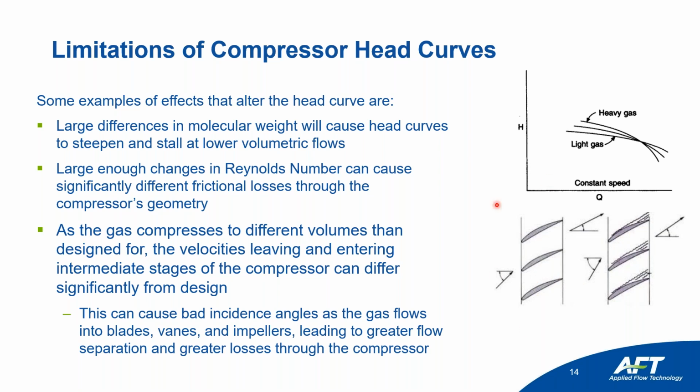or the first rotor and stator, or the first impeller, is going to be pretty much the same, you're going to get a different outlet pressure and a different outlet volume. And more specifically, because the volume is different, you're going to get a different velocity coming out of that first stage and into the next stage. Now that can cause a very bad incidence angle for your